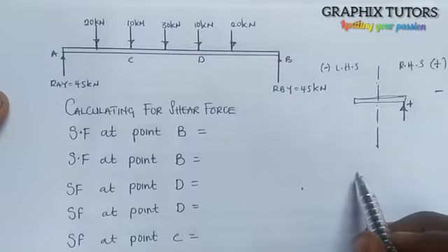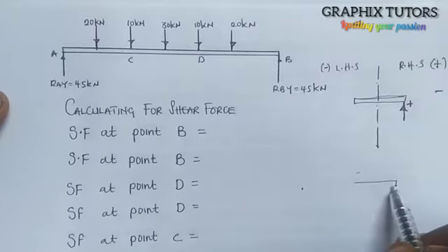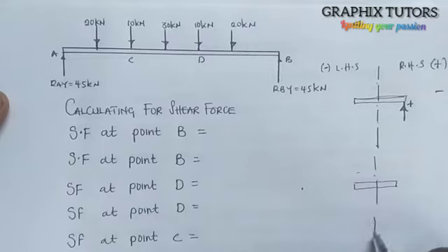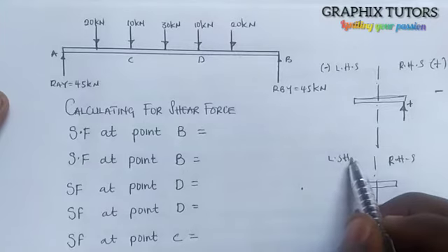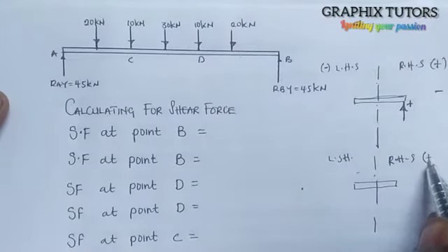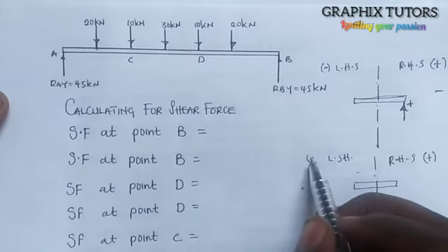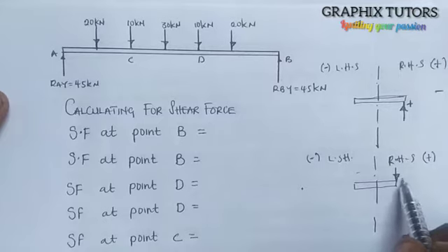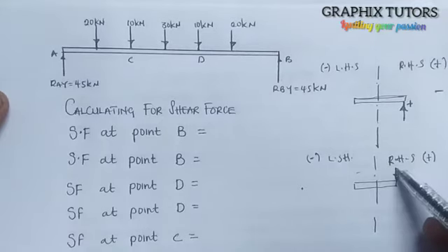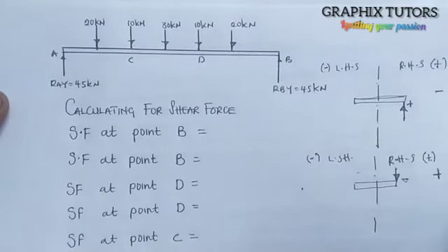Similarly, if I have that same beam this way, and I section it, you know this is the right hand side, and this is the left hand side. Like I said earlier, the right hand domain is positive, the left hand domain is negative. So if the force is facing down, when the force is facing down it is negative. Now since the force is negative and the domain the force finds itself in is positive, and they are different, you say the shear force is positive. Now let's stick with that. Since we are coming from the right hand side, let's stick with that.